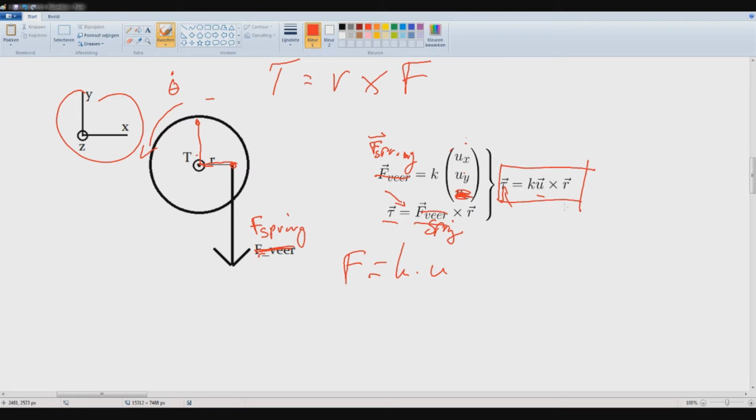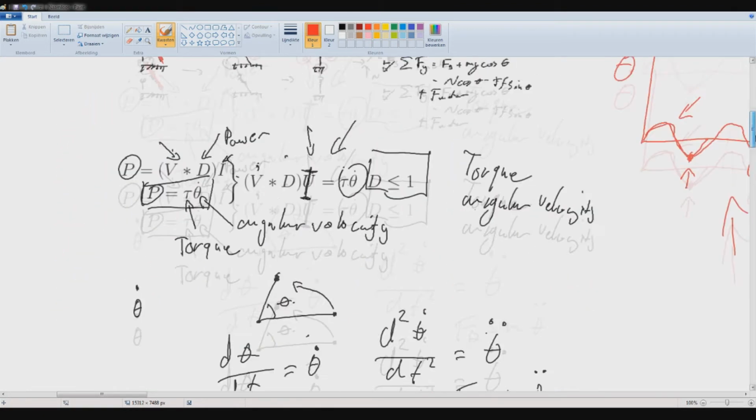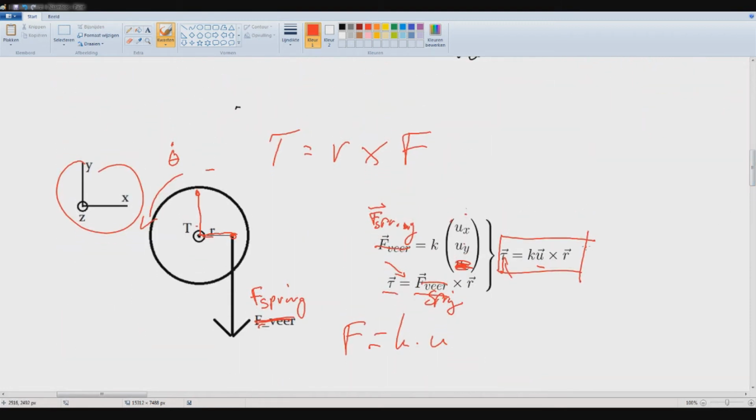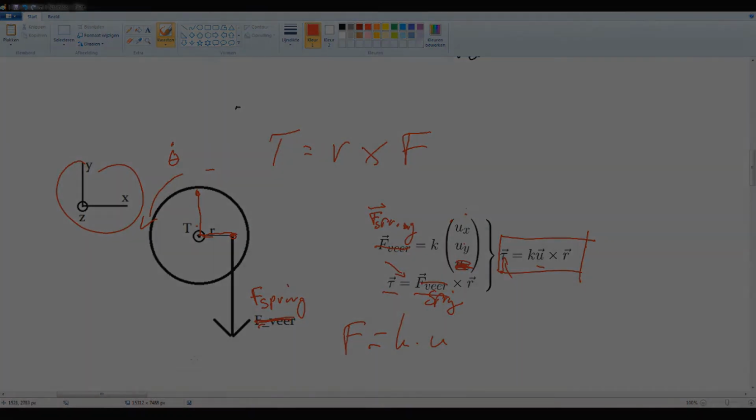That's applied to the motor, which we have to control. Well, we can't control the torque, but we can control the angular velocity component to be a constant, because if the torque goes up, we just give it more voltage, and therefore the velocity goes up, because the torque is mostly a function of a sine function, and so we can keep the angular velocity constant. And why that is necessary, we will see now.